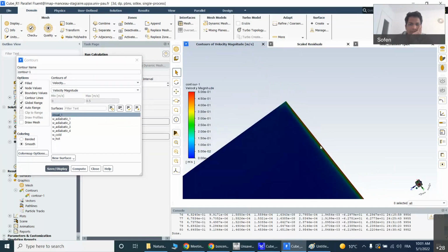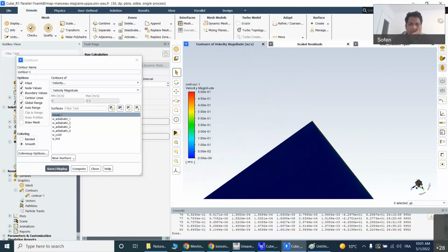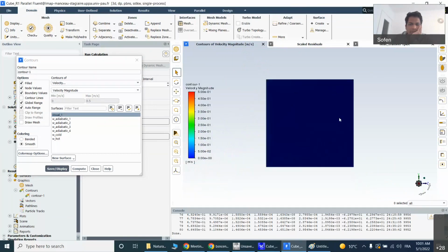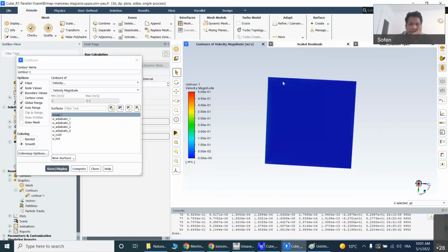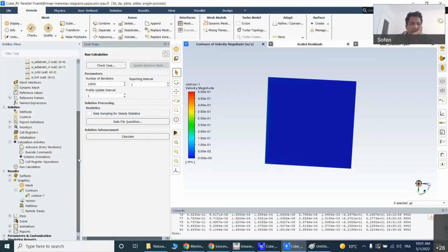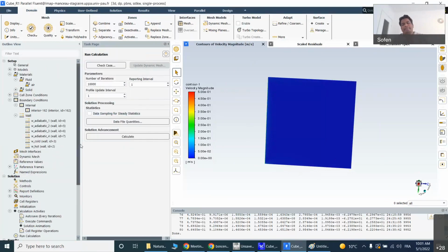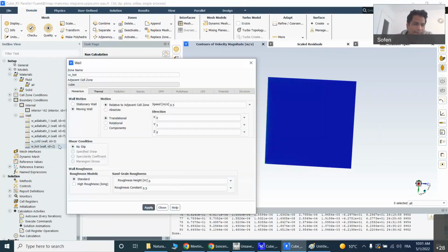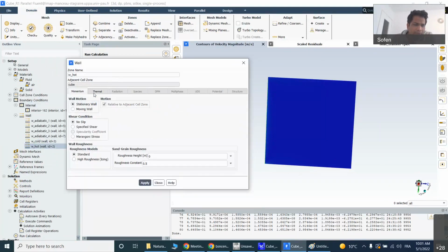Gradually the velocity is diffusing. It will come like a rotational structure. You can see this structure because of the lid-driven cavity. It will take some time to generate the result, in 3D. Now, let's switch on the stationary wall, make it stationary, and focus purely on natural convection.